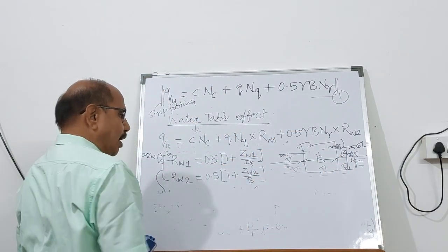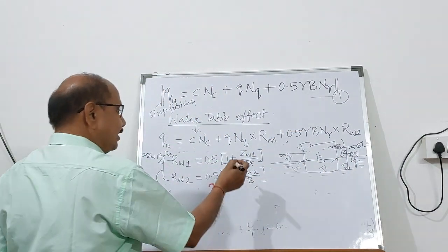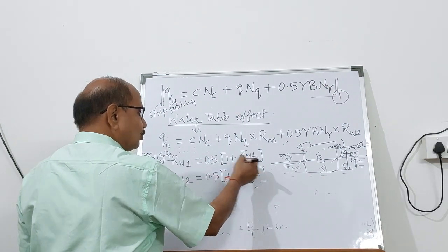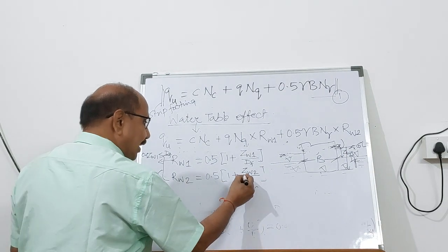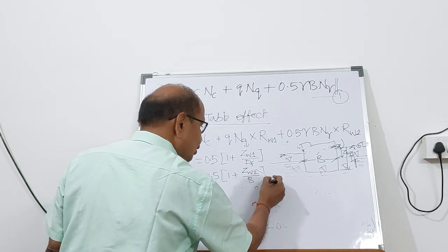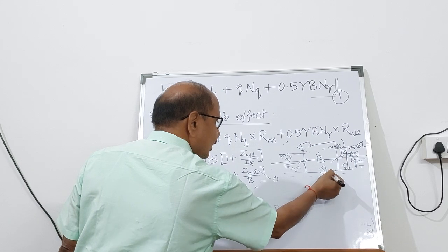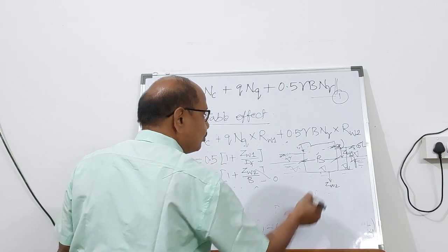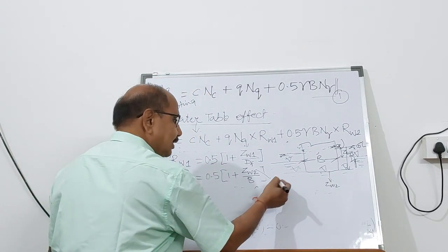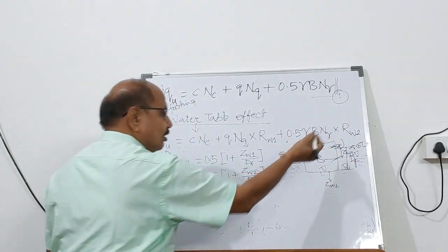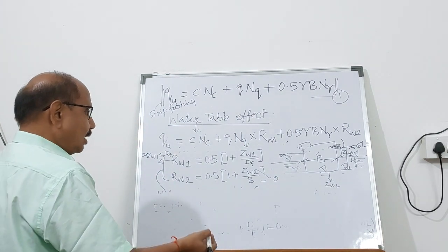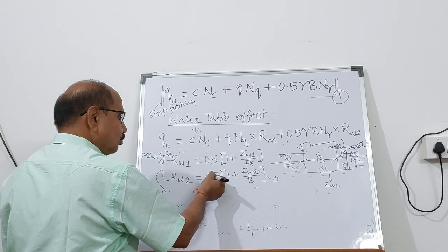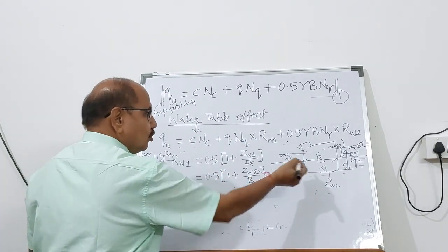It has gone up, so ZW1 is less than DF and you can substitute the value of ZW1. But ZW2 is going to be 0 because it is measured below the base of the foundation, and the water table has gone up. So this becomes 0, and 0.5 into 1 becomes equal to 0.5.